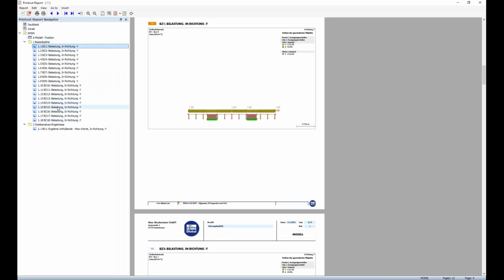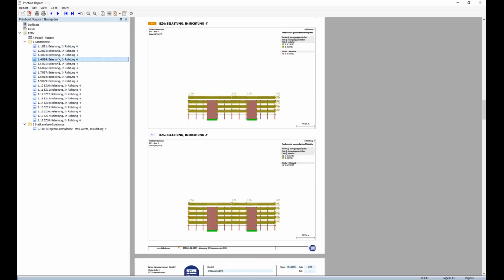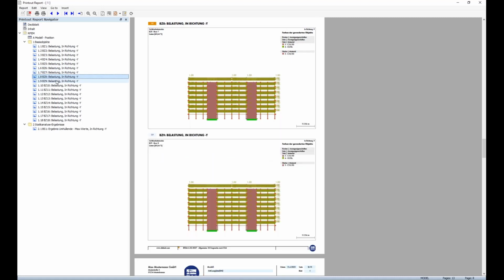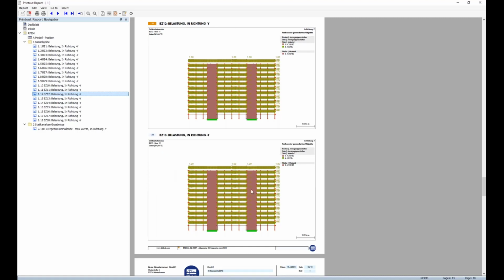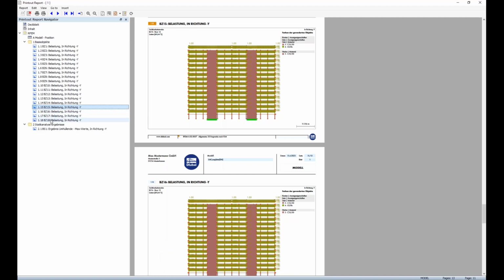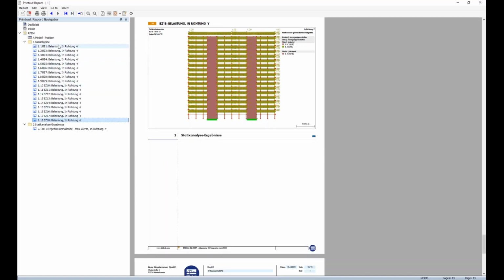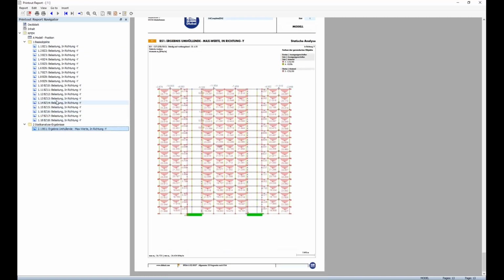So here, for example, you could use the multi-print together with the object construction stage, and you could print for each construction stage the structure with its permanent loading. In this example, there was the self weight, which is not shown in this picture. Here is only shown the additional dead load. Yeah, and you could print it using multi-print, and of course you could also print the results as for a common structure. So there is nothing more special about it.